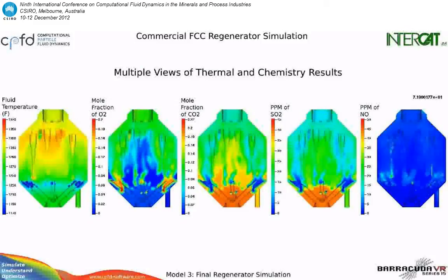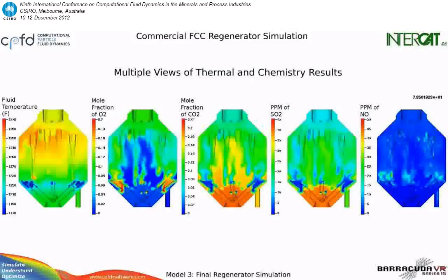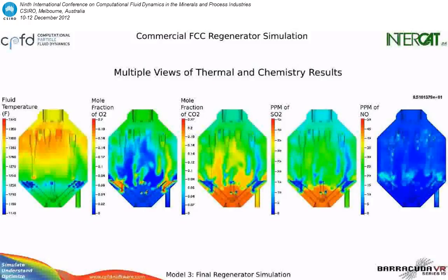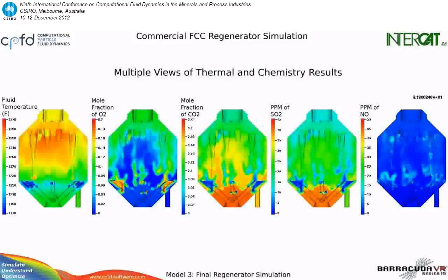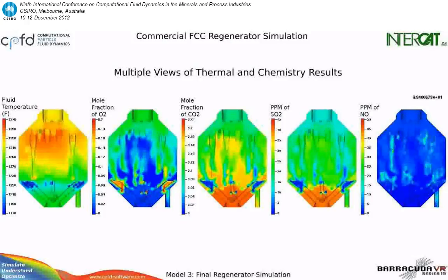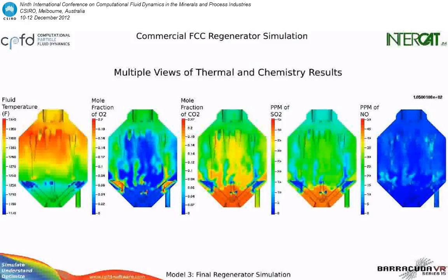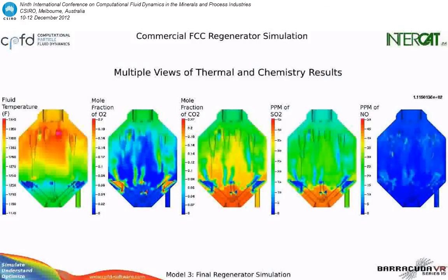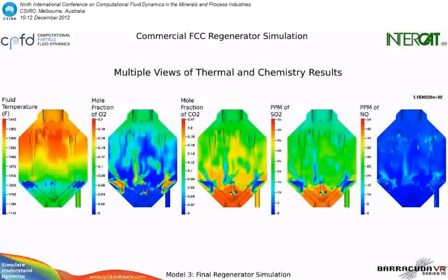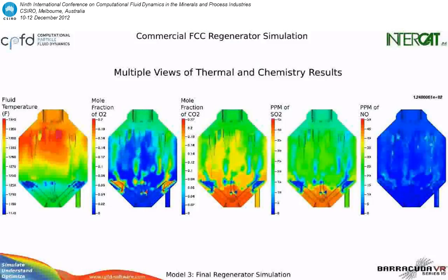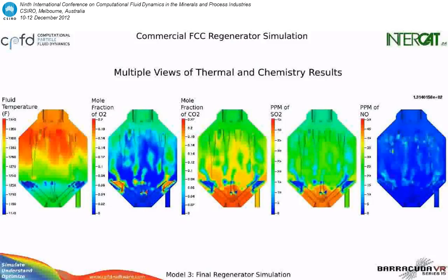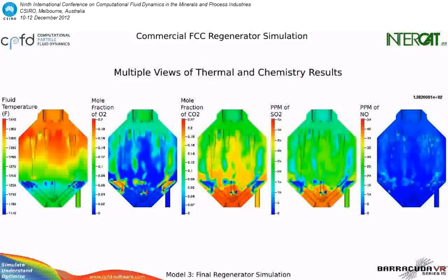So there's an excess amount of combustion air which is bypassing the bed, leaving the center of the bed, if you notice the figure second from the left, oxygen starved. So there's essentially a deficiency of oxygen in the center of the bed, and an excess of catalyst. This suggests several different ways to address the afterburn phenomenon, including either putting less cat into the center of the bed or putting more air into the center of the bed, both of which were suggested to the operator as possibilities.